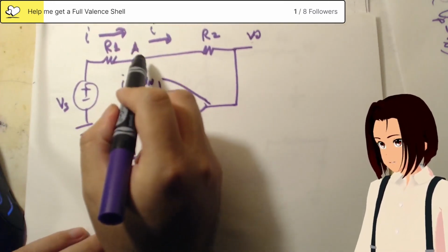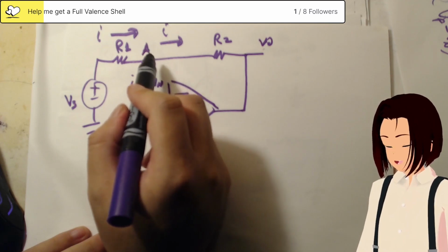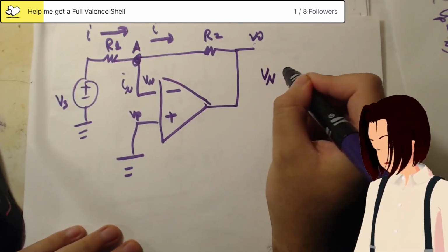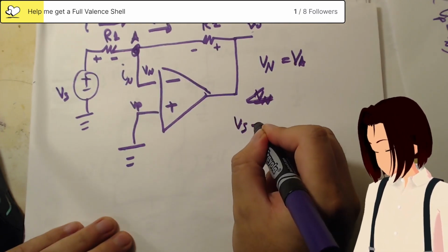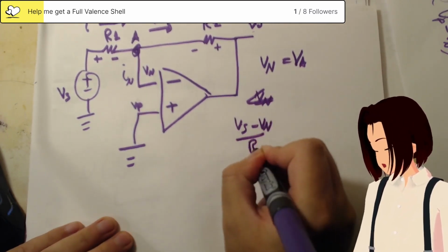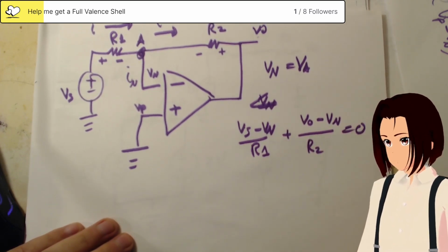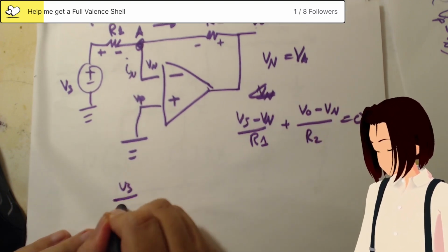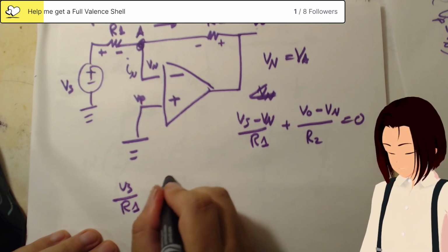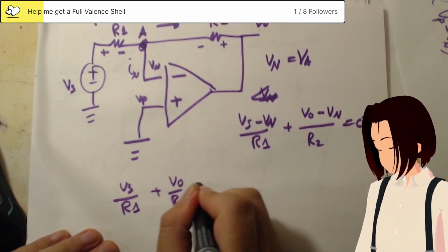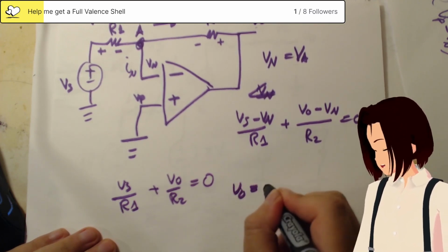We're going to look at this node, node A. We know the current going in is the same as the current going out. So we know V in is the same voltage as VA. So we know that (Vs minus V in) over R1 plus V out over R2 is equal to 0, because the currents are the same. So therefore, we have V out equal to...